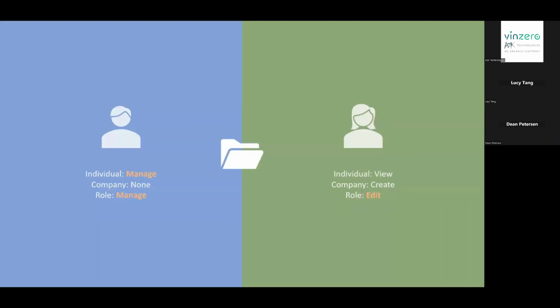Now, combining what we now know about each permission level with the ability to assign permissions on an individual, company, and role basis, there can be some confusion on what level permission a user actually has. For simplicity, let's say we have one folder we're assigning 2 members permissions to. So Jake here, we've assigned him to this folder as an individual with a manage permission. His company has no rights to this folder, and his role as a BIM manager also has the manage permission to this folder.